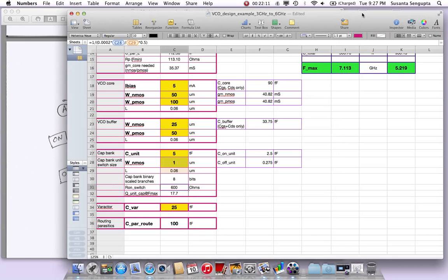So let's see, what did I use for VGS minus VT here. I've used 0.5 volts. Just that same formula, I put it here with a VGS minus VT of half a volt. Because the threshold voltage is 1 volt and this is like a 1 volt or 1.2 volt design, VGS minus VT is going to become roughly half a volt, and that gives you an R-on of this. So the switch has an on resistance of this.